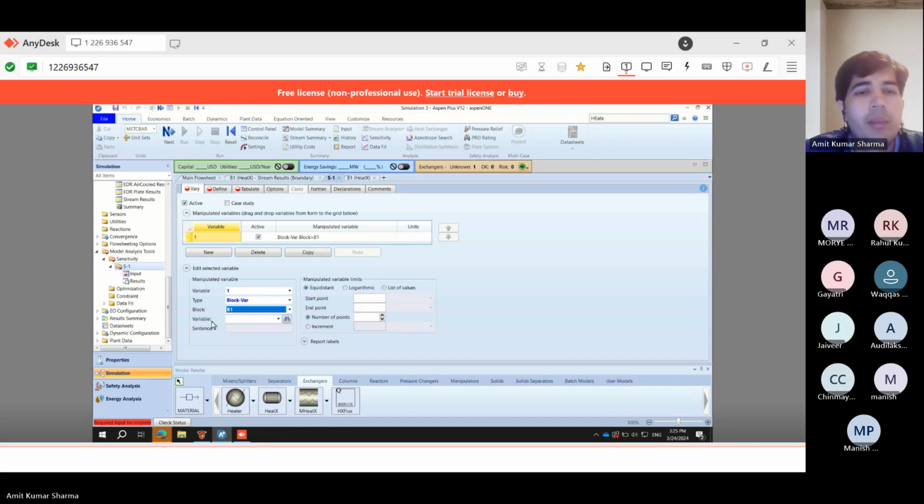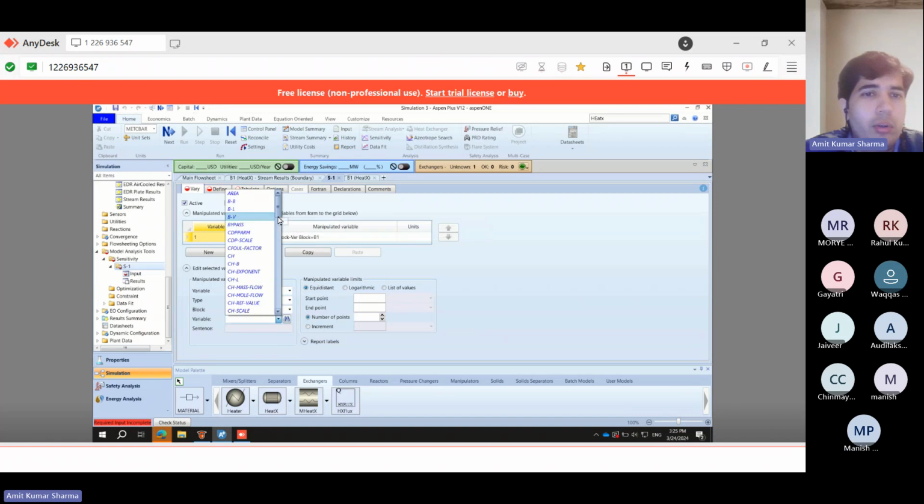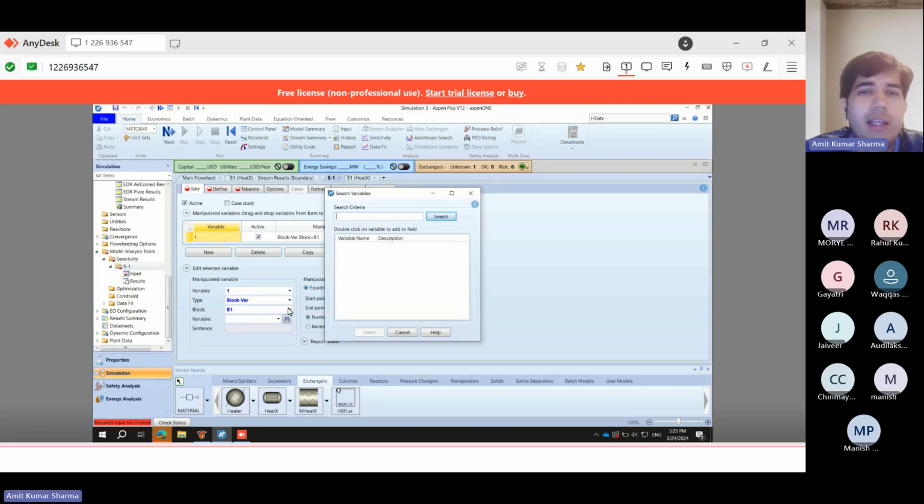Select B1. Now what is the variable? Because we don't know the exact name, but we know we want to vary the heat exchanger duty, go to this search criteria. Now type here: exchanger duty.